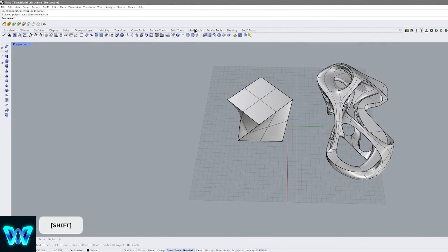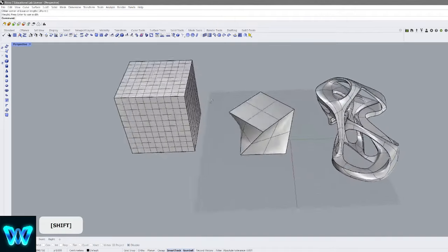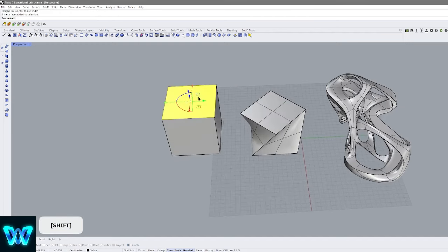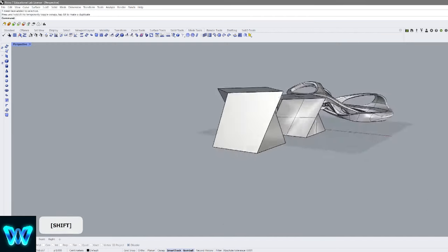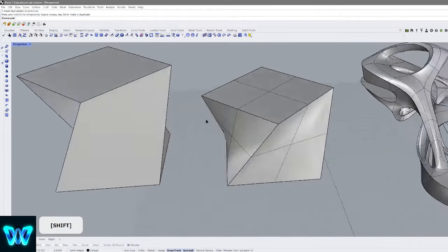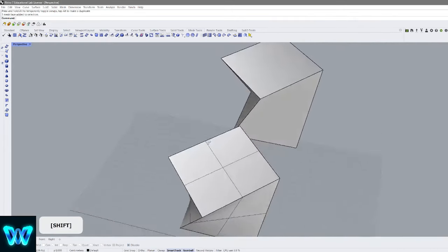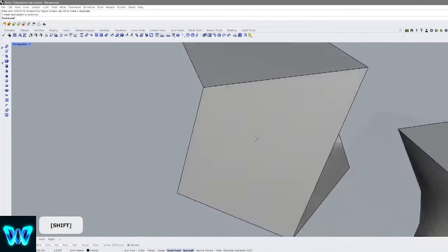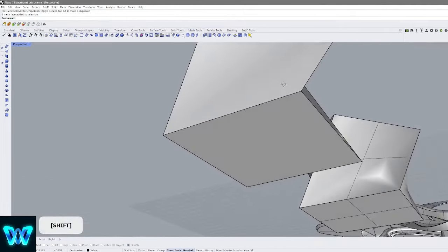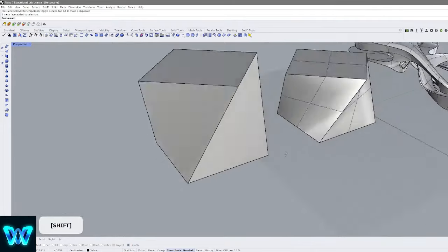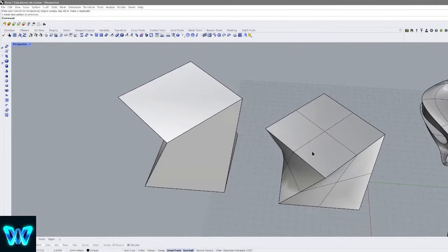The other type of thing that we have is mesh tools, which in this case is literally a mesh. The mesh is the most basic type of geometry, and if we were to make it simple, where there's only one face, just like this cube, and we were to twist it, how we twisted this cube, in theory these faces are not bending how this one is bending. So these faces right here are technically broken. If we were to use it for 3D printing or something like that, it probably wouldn't work very well. And as you can see, they're sort of splitting the surface, right? In this case, you see how it's creating that curve, because NURBS understands when the surface is being modified.